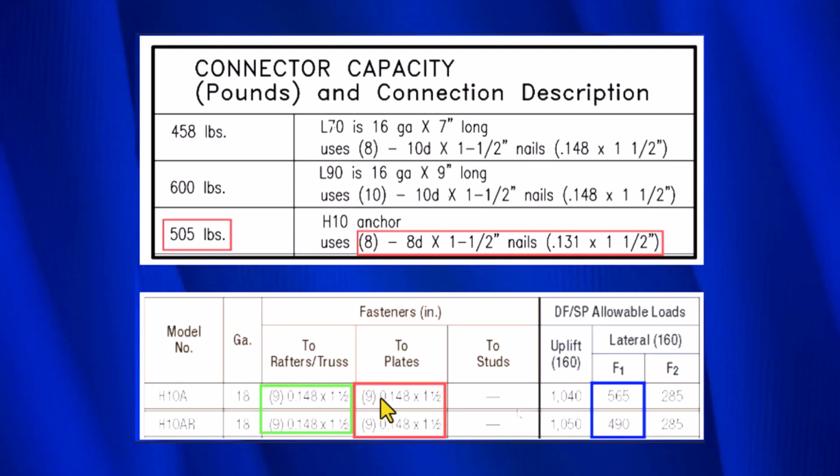So this is really, really in bad shape, because if a contractor comes in here and goes, oh, I just have to put in 8 nails, he'll put in 8 nails wherever he wants to put them in, and the value of that hardware will be worth absolutely zero. Simpson will not recognize hardware that is installed with only 8 nails. When it's supposed to have 18 nails, they will not consider it as having any value at all.